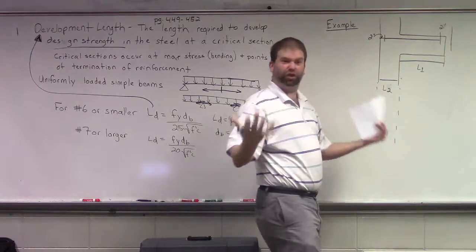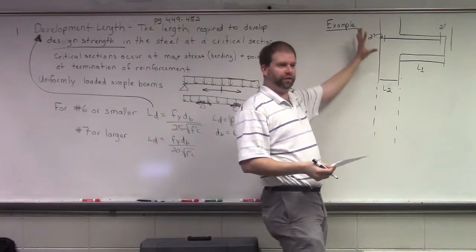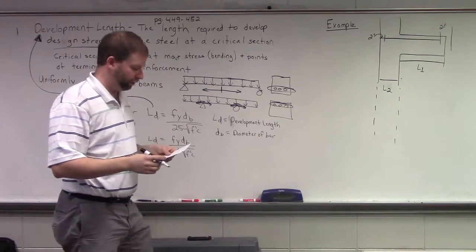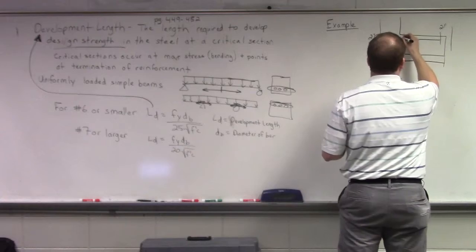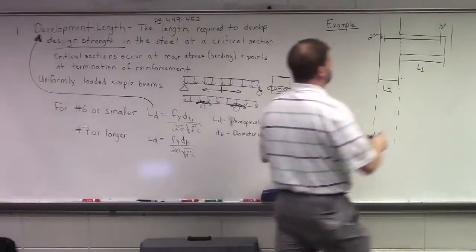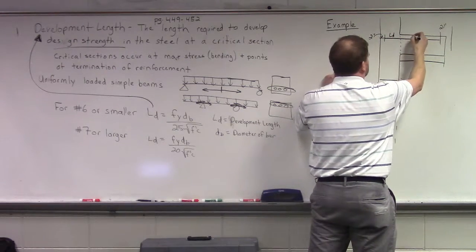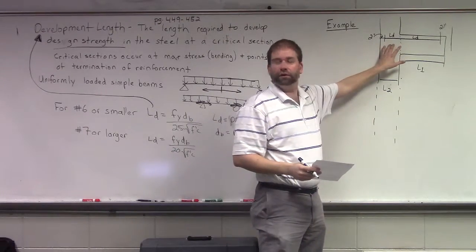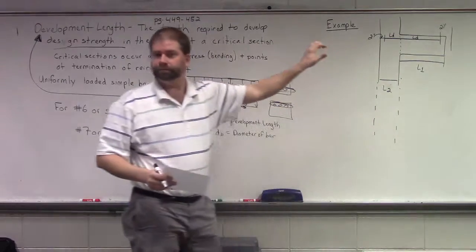I guess I should say we're assuming we're working with formed faces, right? I'm not assuming that we cast this thing right up into some wall. Probably didn't work out too well with our geometry. Okay? So what we'll find is that based on these stresses, based on how these things are going to work, we're going to have 2 development lengths. We're going to have our development length within our wall. We're going to have our development length outside in the cantilever section. Okay?